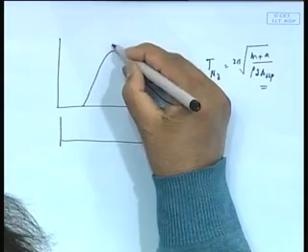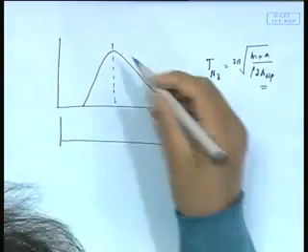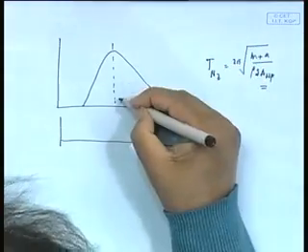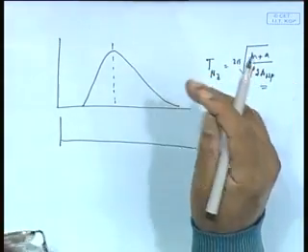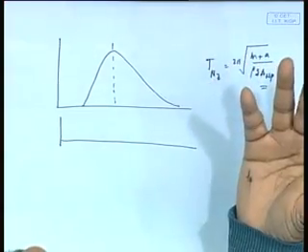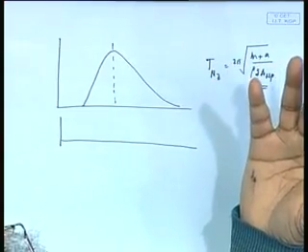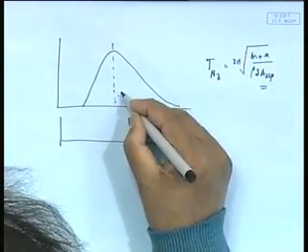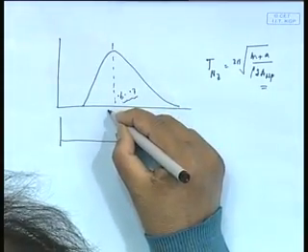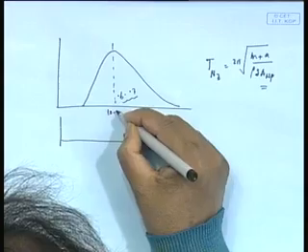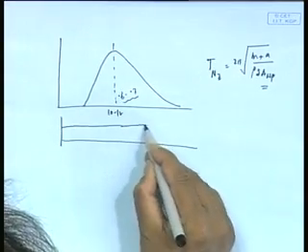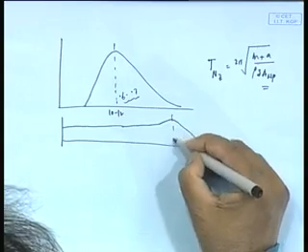So, I took a typical wave which looks like that. Typical wave, everyday wave of say sea state 4 etc. will have about 10-second period, means omega equal to 2 pi by 10 would give you about 0.6, 0.7 like that, okay, in that region, say 0.6, 0.7 somewhere here, or it is basically equal to say 10 to 12 seconds. But remember this low wave, so this will look something like that, go like that, because this natural period is much higher.